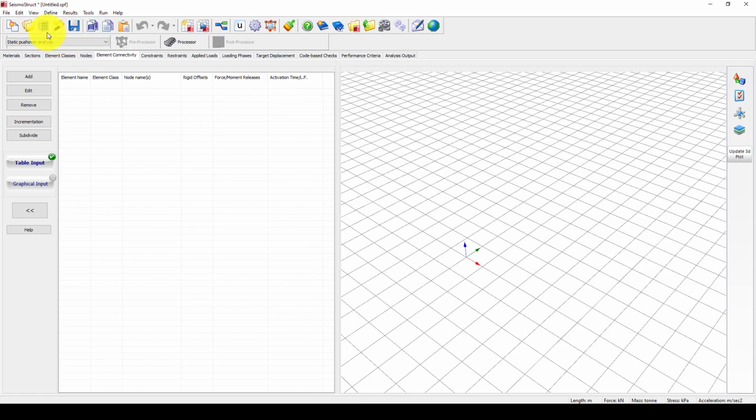Now the analysis is completed, and it took 10 minutes 32 seconds. Before we go to the deformation part, let's see here in the output log, and here are those elements which have already reached yield, and it's giving us the time step of 3.61 seconds. This element, which is a first floor column, has reinforcement strain that reached this value, which means yield. And also this one, which is a beam, has already reached yield.